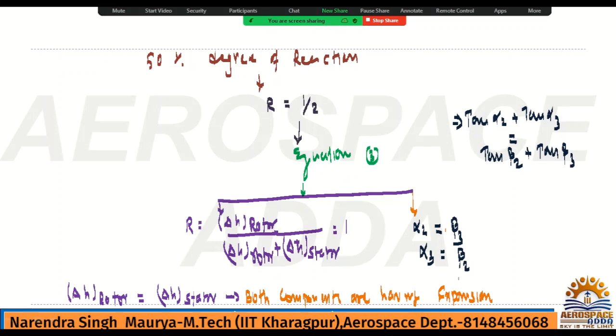Yes or no? Both, if you check. Now what does this indicate? Where is the angle alpha 2? In terms of the velocity components in the compressor, as I explained, alpha is the air angle which relates to the absolute velocity. The absolute velocity component in the tangential direction is CT2. For the relative velocity, because it is beta 3, it is WT3. I have explained this in the compressor lecture, so please go and watch it; I am not going to explain it again because it will take time.